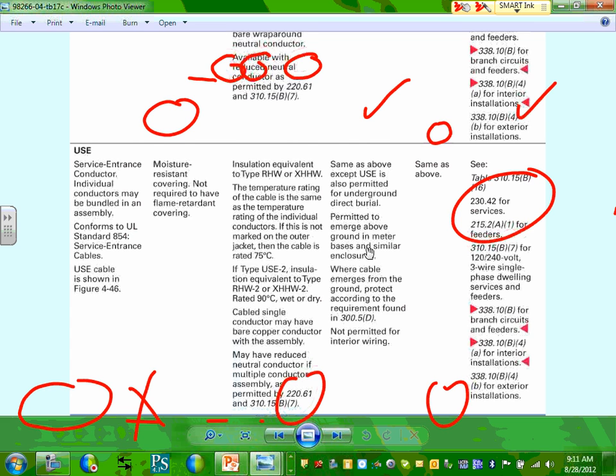We use them a lot in, as I said, farming, Jeff, when we go from building to building, from pole to building 1, building 2, building 3, and so forth. Any comments, any questions, guys, about these wiring methods? So between USE, SE, SER, we have 3 cables, 6 with the others, and conduits 4. That will give me 10, close to 12 wiring methods that they're going over.